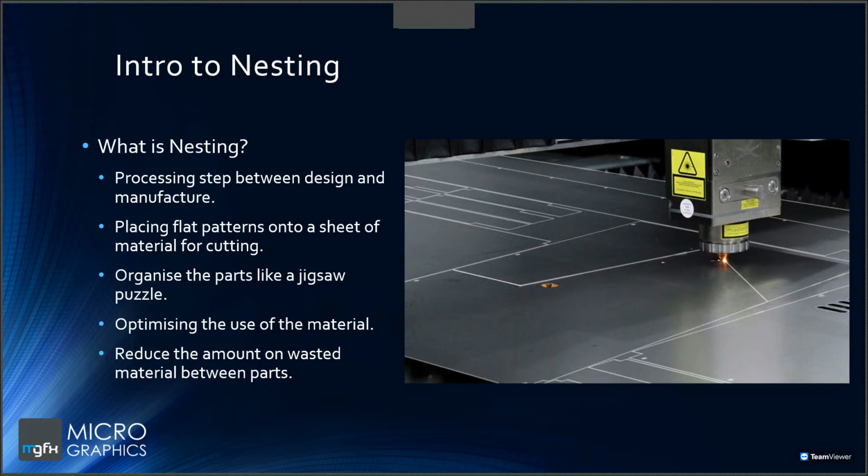And also when nesting, you need to take into account single-faced materials, and these considerations will be discussed later on in the webinar when we start looking at nesting settings. So the goal of the nesting is basically to organize your parts onto a sheet, optimizing the use of that material, and therefore reducing the amount of wasted material between the parts. The end goal here is basically to save you money once all those components are cut.